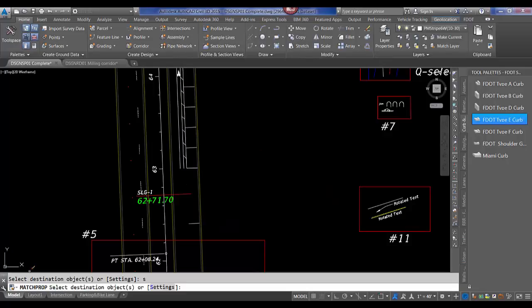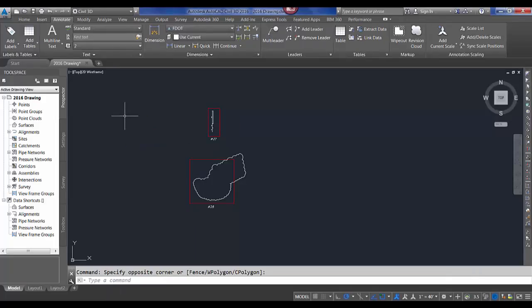Okay, number 16. Now this was introduced in 2016, and it is, let me switch back over here. I'm not going to close anything, but the close all other command. If I type in close all other, let's say I had 10 files open, and I've got my current file here, and I don't want to close it, but I want everything else to close.